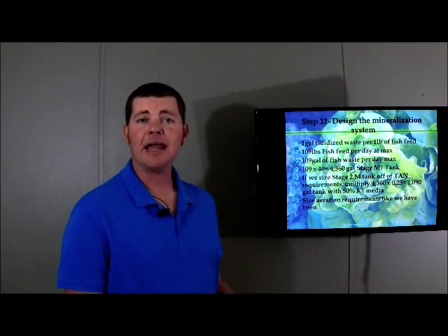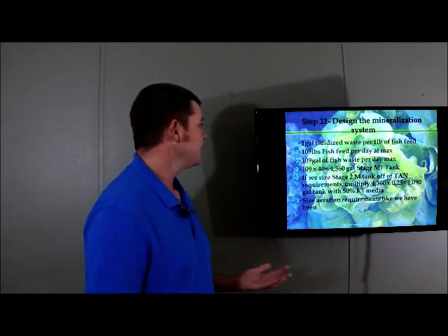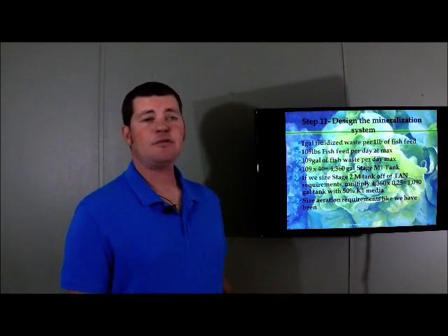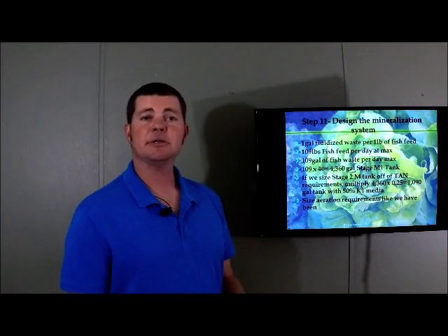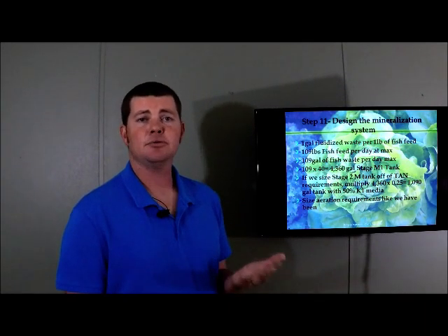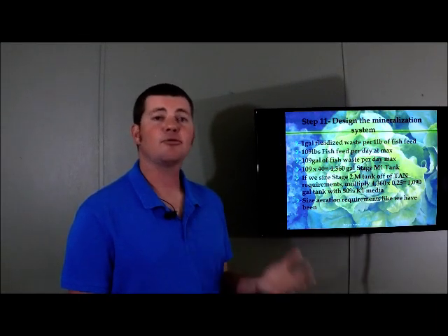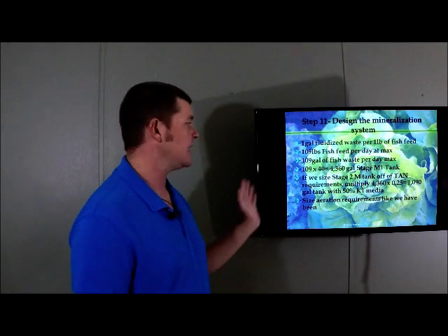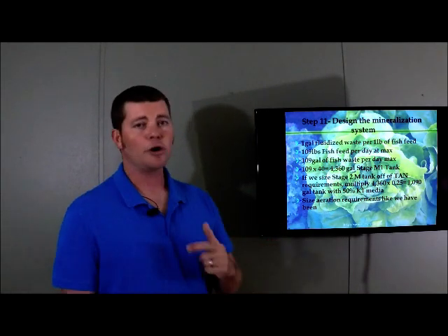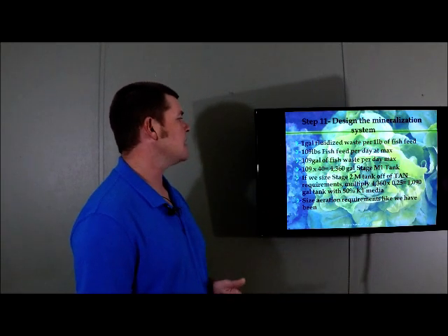Okay, we're basically creating a wastewater treatment plant at this scale. That's what we're doing. Takes up a little bit more area. If you don't want to include mineralization tanks in your design, you don't have to, okay? That's something up to the designer. The fish production will be much higher in relation to the plant production if you negate the mineralization tank. But you already know that by now, okay? So we got 4,360 gallons of stage 1.